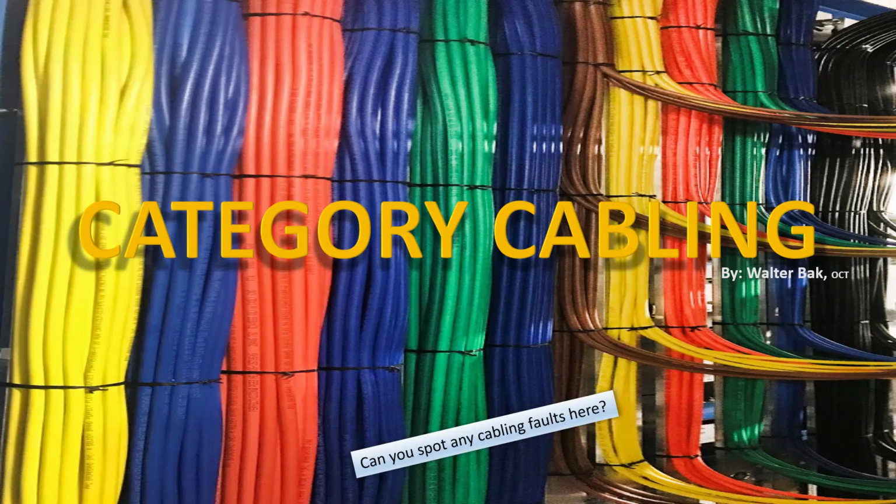It's better to just pull it out and run another cable in its place. So you have to be really, really careful when you're working on construction sites, when you are laying cables on the floor, to pull up some extra slack, because you have to pull cable from one place to another and you need some kind of intermediate location. So you pull a slack on that, make a loop, and then keep pulling because you have to go over some obstacles or something like that.